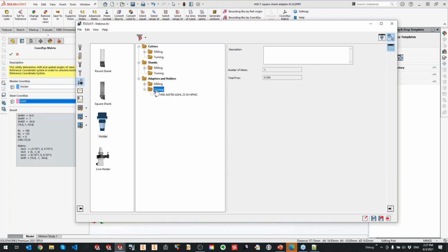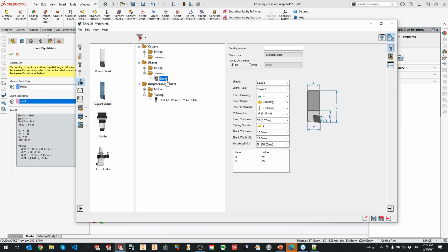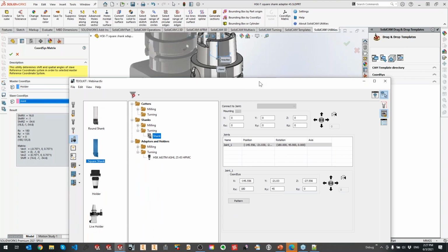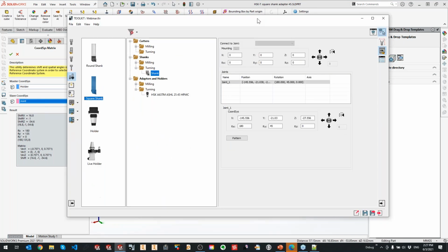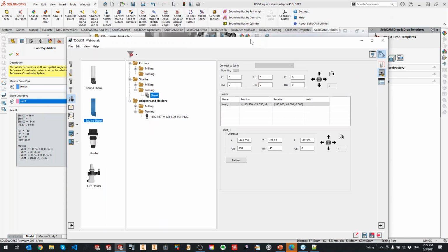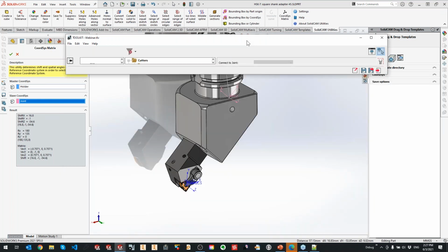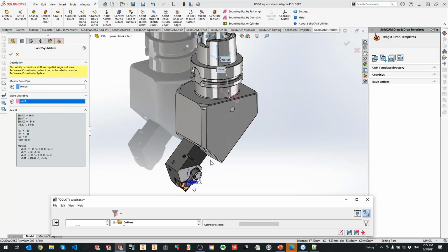All right, so this is for my turning tool holder, and now we are going to use the shank. It's a square shank, so I'm just doing a drag and drop. Let me do a connection, of course. You can also minimize it with Control Shift. So for all of you guys who don't know about this, for the active window, you can do a Control Shift in any way, so it will kind of minimize, so you can play with this.